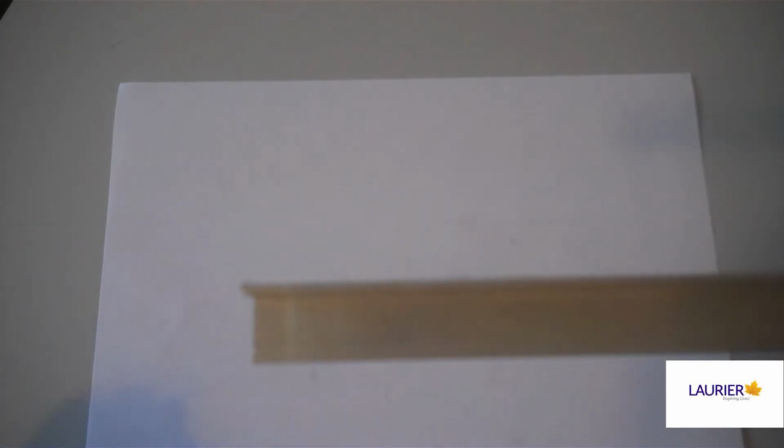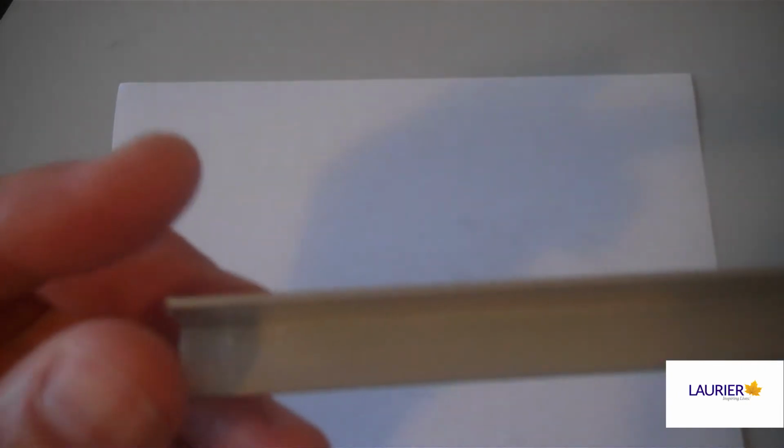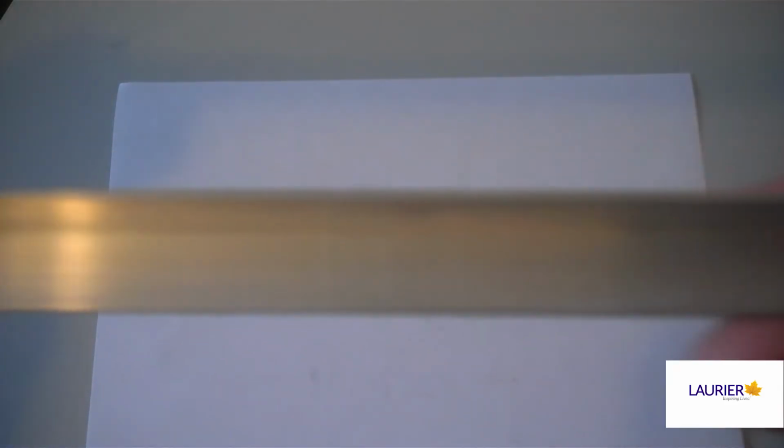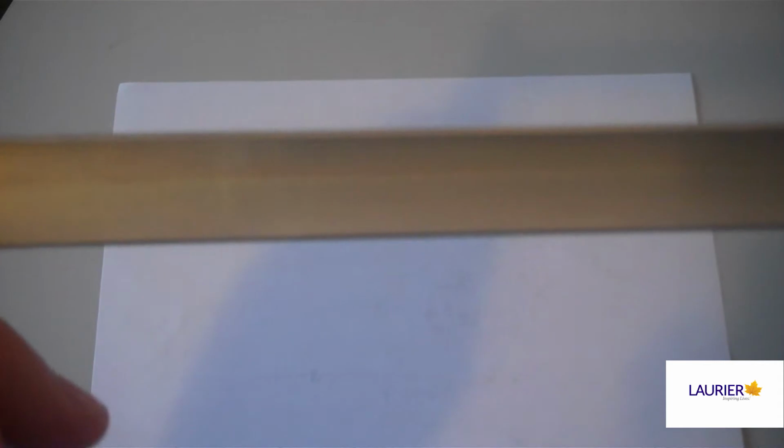So why are we talking about extrusion when we're talking about CAD? Well, we do it because SolidWorks makes a solid model by extruding a two-dimensional cross-sectional shape that's called a closed contour up off of the plane it was drawn on and through space. What this means is that any new part or feature is always starting as a two-dimensional drawing that sets the cross-sectional shape for this feature.